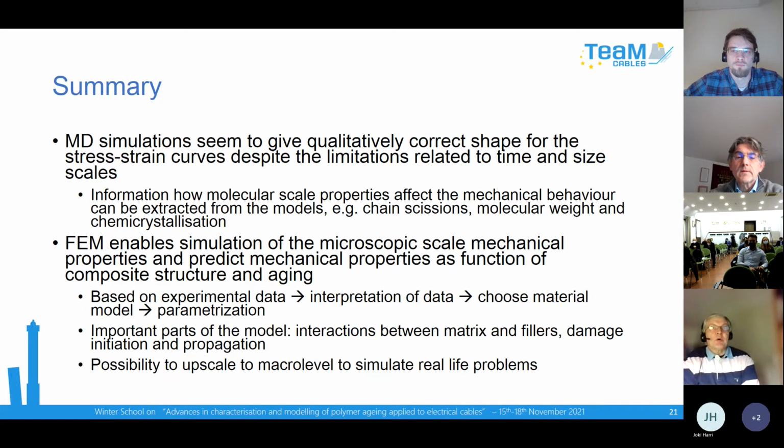Yes, well, what we do in the simulation, we define these chemical bonds when we are introducing the chemical crosslinks. So that really ties the chains tightly together, so that doesn't allow the relative movement of the chains with respect to each other. But if we have entanglement, then the chains can actually move around each other. It's sort of implicitly taken into account by the model.